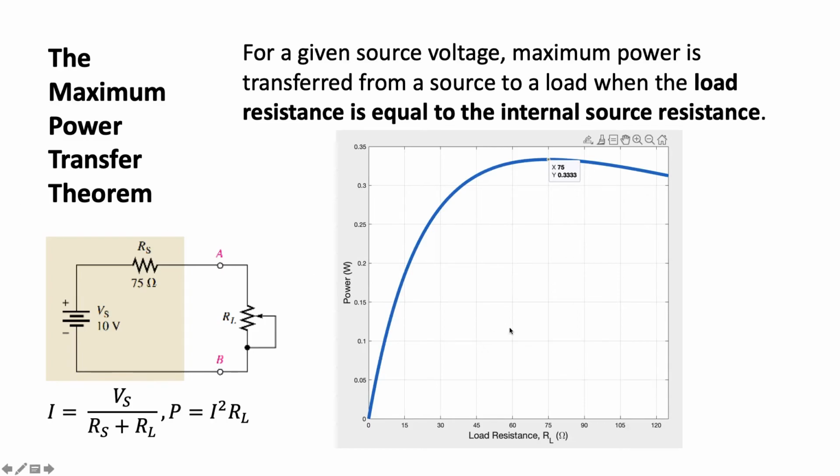You can see that the maximum power transferred to the load resistance occurs when the load resistance is equal to the internal resistance of the source. Thus, in order to have minimal losses, you must make sure that the load resistance matches the internal resistance of the power supply. In practice, this is very hard to achieve and some compromises must be made.